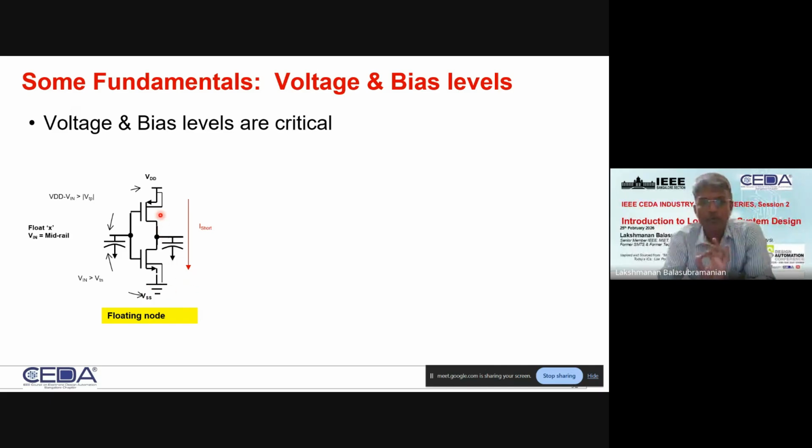But effectively what it means is, in normal operation of the transistor or devices, this is going to consume a certain amount of dynamic power only during the activity when it charges and discharges. But under this condition, this is going to consume a DC current, which is limited only by the max capacity of these transistors, right? So there's going to be a huge amount of current.